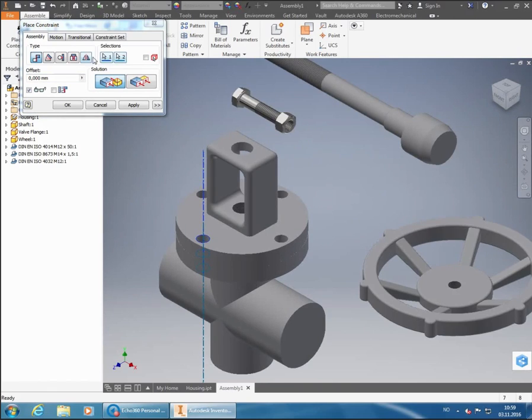One way I can show this a little bit better is if I deselect the first one I did here, just to signify what's actually happening here. If I select this hole instead, over on the side here, it's going to rotate the flange 90 degrees until they are on top of each other. So it means that it has put this hole on top of the other hole. And this was the reason why we needed at least one hole in the lower flange, because we needed to align it this way. So once we've done that, we're going to click Apply.